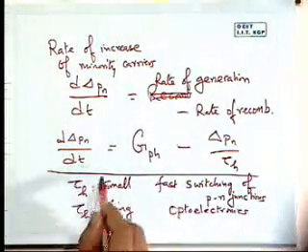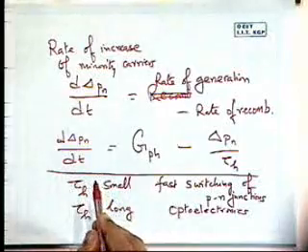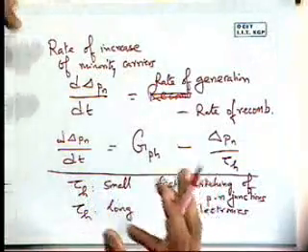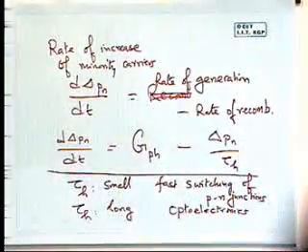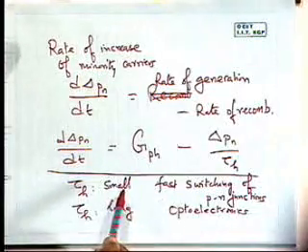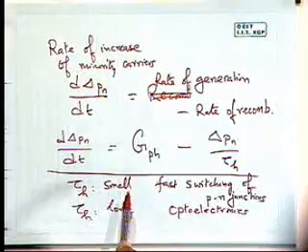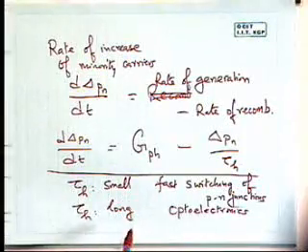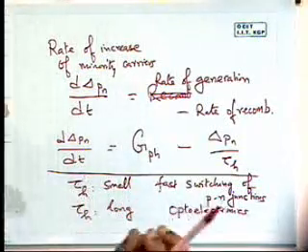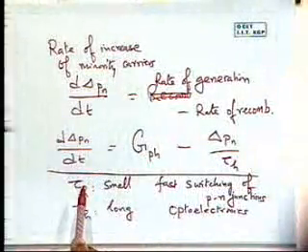Then, as I mentioned earlier, this is determined by defect structure. So a particular crystal or a particular device that has been fabricated may be good for one application. It's the same semiconductor or the same junction, but it may not be good for the other application, simply because the defect structure is such as to control and affect the lifetime that is there.